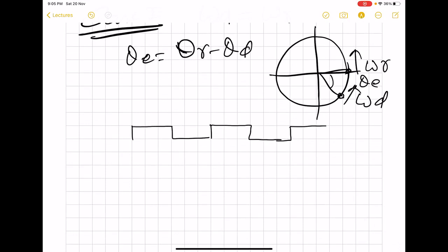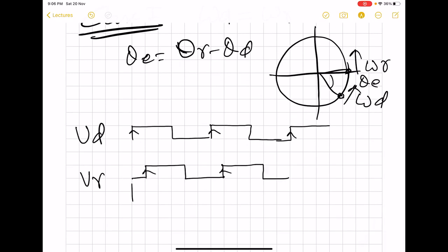Here we will see that we need not create a pulse out of these two input signals. These signals in their natural form, in this clock form, are enough to get the meaningful output from this phase frequency detector. Here we have this much of phase error between the two signals.